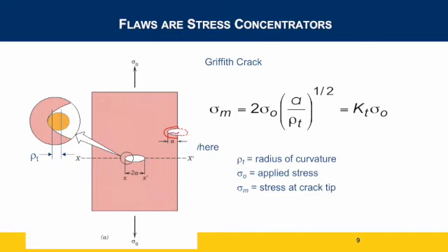We call that A, and that is the length or half the length of the crack, right? So if it was inside the material, we would have both sides of the void. So our A would be the center to the side, that would be A. So obviously the diameter all the way across the void would be 2A. So if it's on the surface, it has a radius of A. If it's embedded in the material, it's going to have a diameter of 2A.